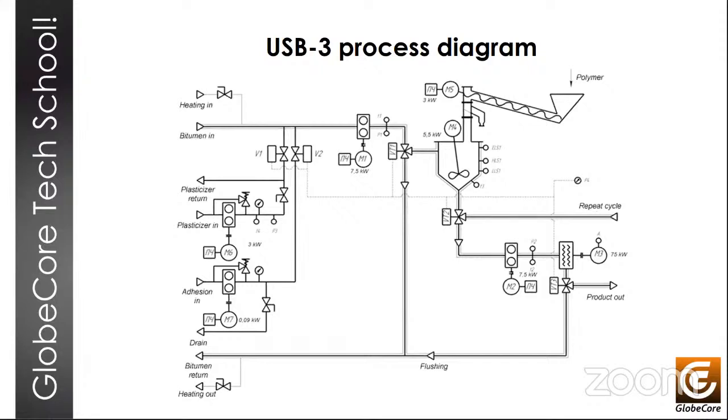And before the M2 pump, the bitumen is mixed with the polymer using the M4 turbine mixer. The operator inputs polymers from bags, like big bags, into the polymer hopper. And then from that hopper, it's fed by an auger conveyor driven by the M5 drive. And depending on the required concentration of polymer and bitumen, the operator can control the speed of the drive and control the auger M5, and thus provide the specified supply of polymer. There is a switch for that on the control cabinet panel.